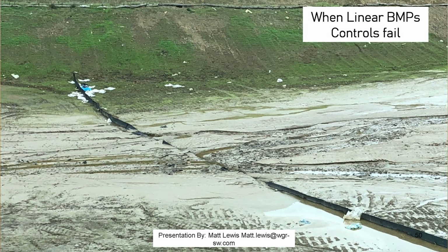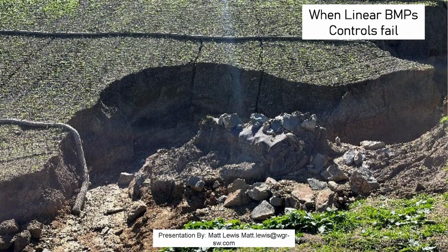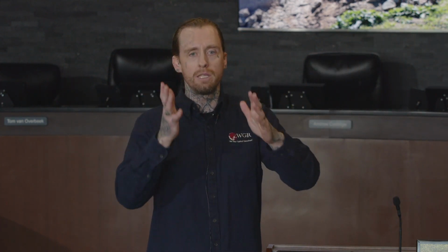So that's something that contractors tend not to want to do, is general maintenance. You know, get back out there. And of course, who wants to go out there and slop around in that mess to reestablish their silt fence? But you've got to do it. And here you can see this is actually the slope of that basin last year. It's kind of hard to tell, but that is definitely a channel. It's not a gully, it's transferred into a channel. And the problem here is that they didn't anticipate the flow properly.